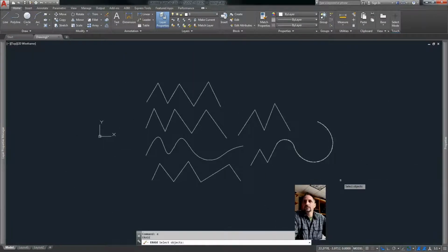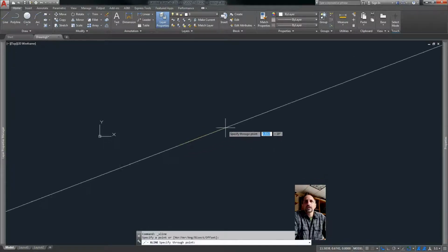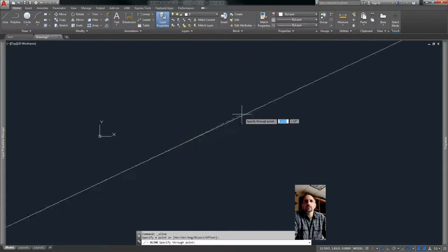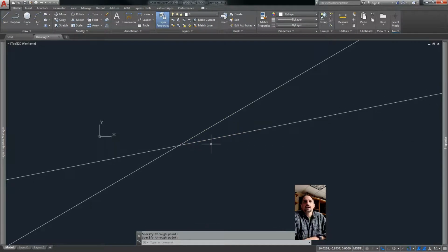All right, so let's clear our drawing space. A couple of additional line commands that you can use. There's the construction line, and you'll notice that we pick 2 points and we get a line that is of infinite length in both directions. This is useful if you have, say, a big drawing and you want to line things up across large spaces.